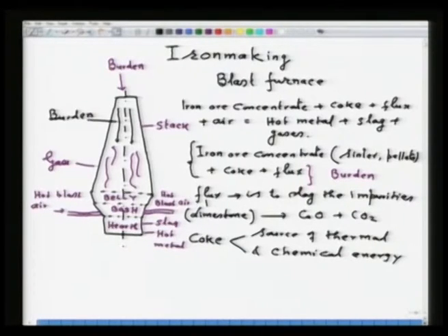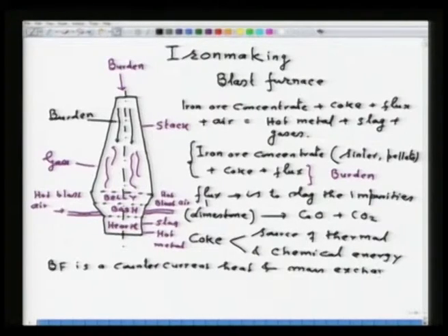So, from a conceptual point of view, the blast furnace, which I will denote by BF, is a counter current heat and mass exchange reactor. Needless to mention, in any counter current heat and mass exchange reactor which consists of gas and solid, the permeability of the bed and the distribution of the burden is a very important issue.